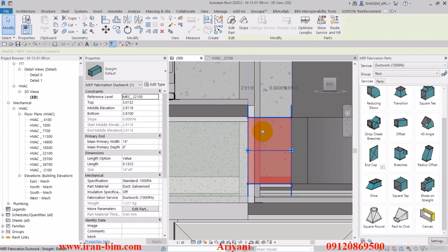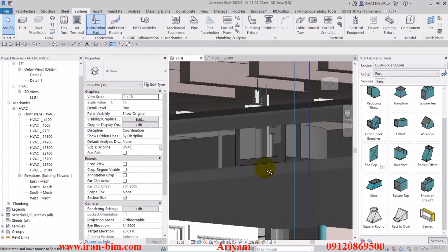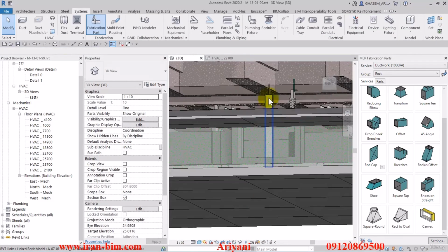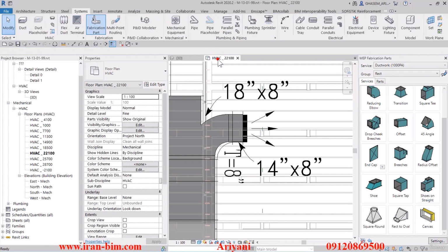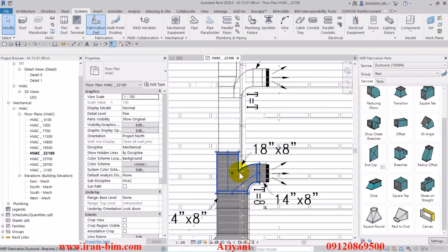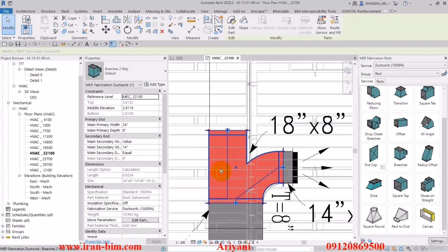And then we'll rotate around it where we can see the wall that we have here in the front of this that needs to be punched through or moved. And as you can see, it's this part right here that's supporting the suspended ceiling. We usually assess these after the mechanic's done, and if there are any changes needing to be made, they'll be done after the work's done. So then I'll go back to the plan and continue the duct that we have here.